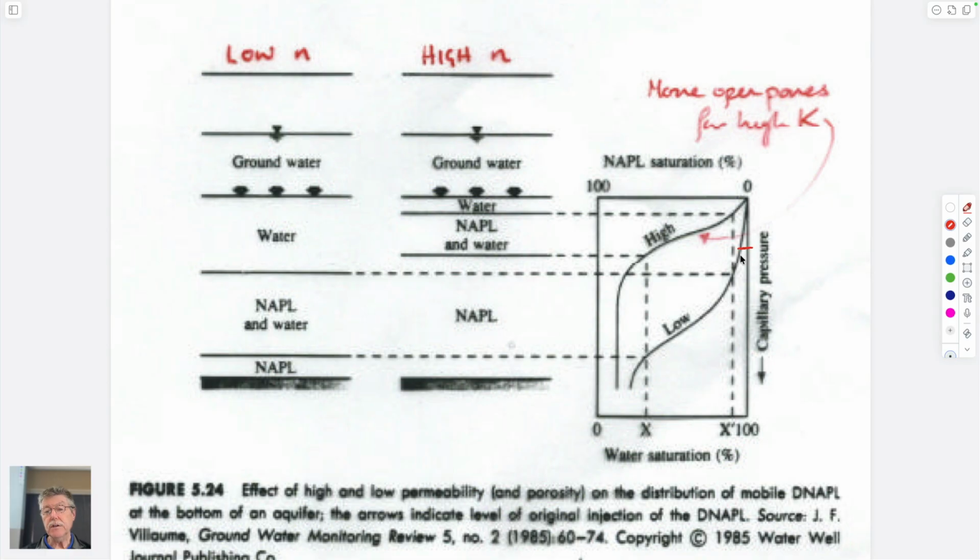And so you'd expect intrinsically from these capillary pressure versus saturation curves to look different, in that this has a large bank of NAPL here, representing this behavior here, because it gets down to this high saturation and then that high saturation continues. And this one represents only getting to high saturations once you get much deeper in depth. And so that's this one over here.